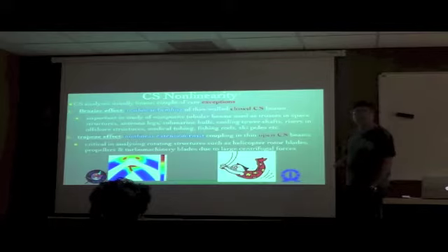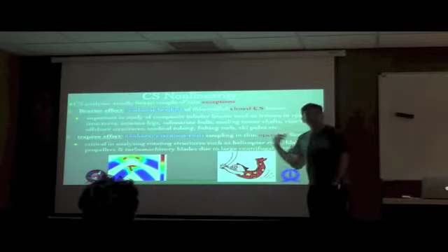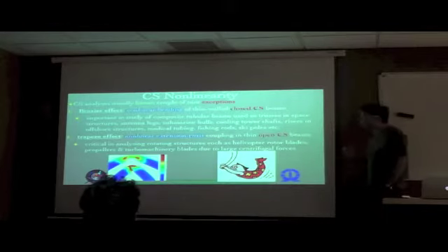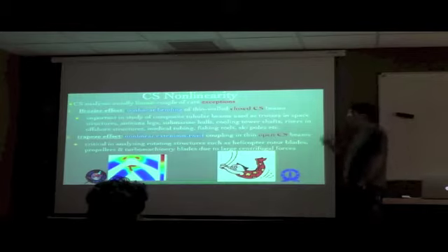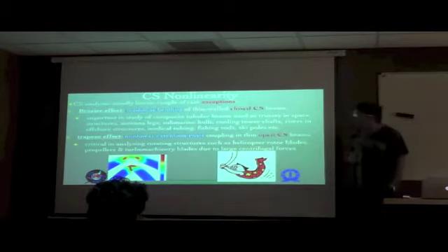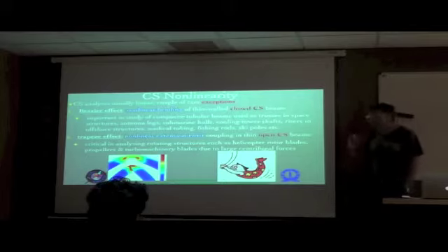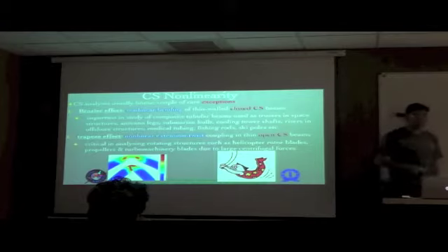So obviously there is extension and torsion in these problems, and the geometry suits our definition as well. Again, turbo machinery blades, not only the compressor and turbine blades that are used in aircraft engines, but other turbo machines commonly used in mechanical engineering as well. And again, in all of these situations, the commonality is the fact that they are all rotating, and therefore large centrifugal forces, which are axial loads, are present.